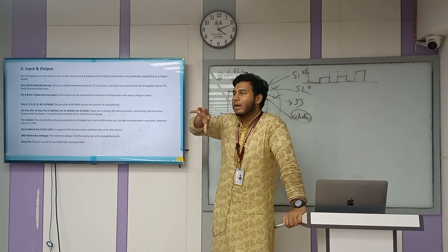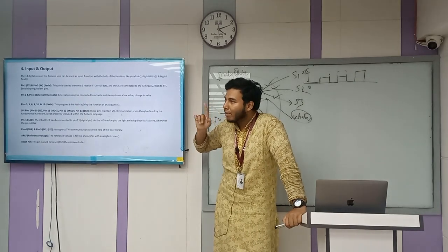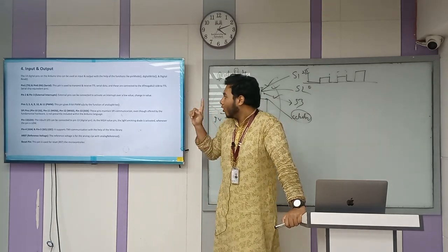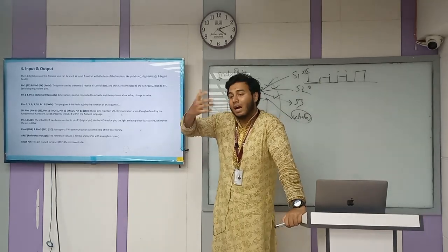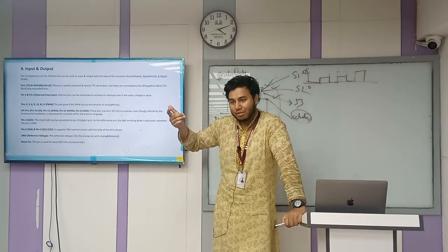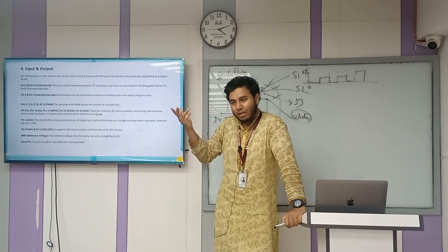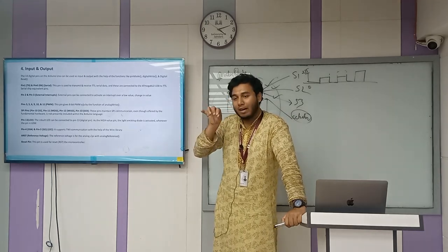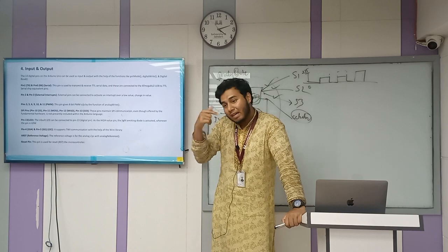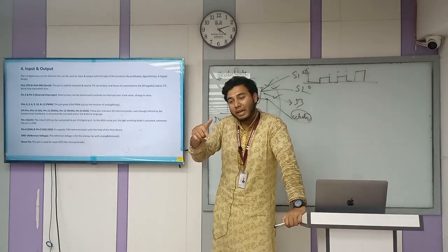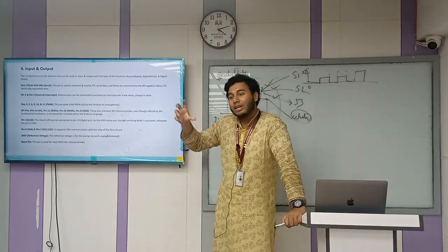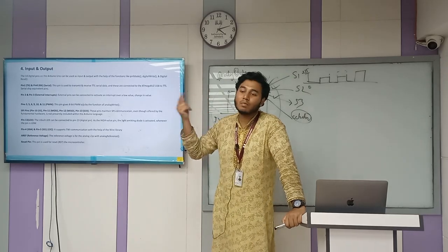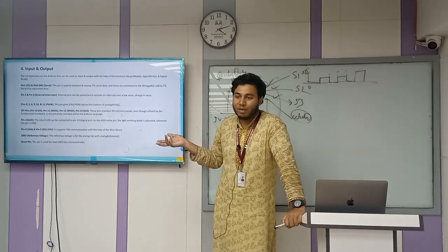You are going to operate a motor, right? That motor is connected with pin number 7. So are you going to declare in code to make pin number 8 or pin number 9 high? No, because you have connected your motor to the Arduino on the specific pin number 7. So you have to declare that you are going to work with pin number 7 and make it high. If it gets high, then I will get the value, and that value will put an extra push to that motor to perform the operations.